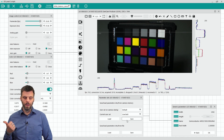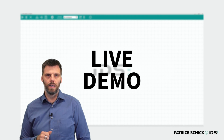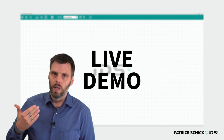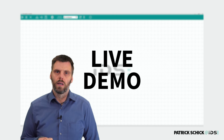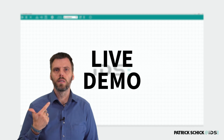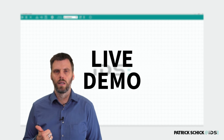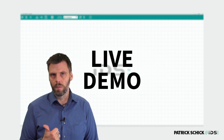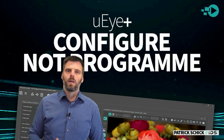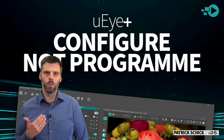Okay, let's switch back to the presentation. This was a short live demo of the IDS Peak Cockpit, where I introduced you to the workspace handling of the cockpit and gave you a hands-on how to set up a camera, exposure time and white balance to get a good image representation, a good color representation, and store this information in a parameter file, so that you are able in your machine vision application to reload this parameter file. I hope I could give you some insights into the new upcoming IDS Peak Cockpit.